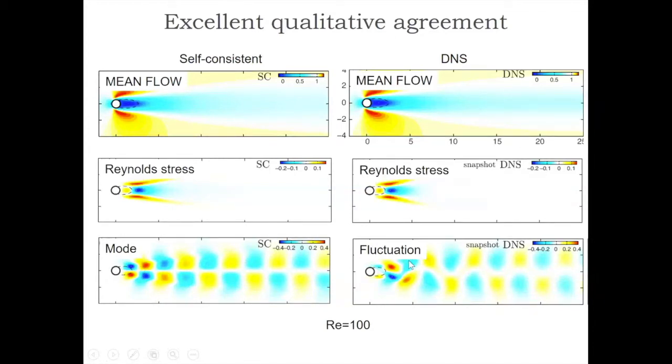The fluctuations are slightly different, exactly because in the fluctuation there is the 2 omega component, which is not important in terms of energetic content, but is very important in terms of symmetry breaking. As noticed by Laurette Tuckerman a couple of years back, the classical double symmetry breaking in the von Karman vortex street, this alternation of vortices, results from that second harmonic vorticity contribution.